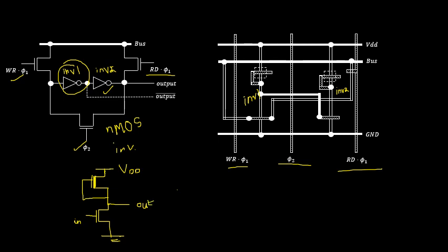Same thing, I have to repeat it once again, so there are two NMOS inverters. So I should have two representations of NMOS inverter in case of the stick diagram, also in case of the circuit diagram. In this I will be having one more transistor connected to the ground terminal and take the output out of this. So this is the VDD terminal and this is the ground terminal, or sometimes VSS also you can take.